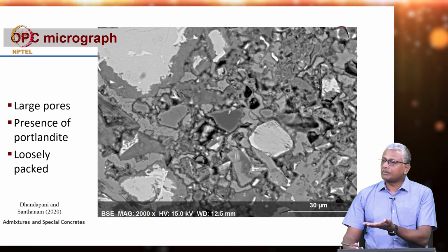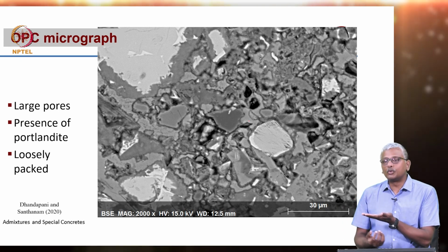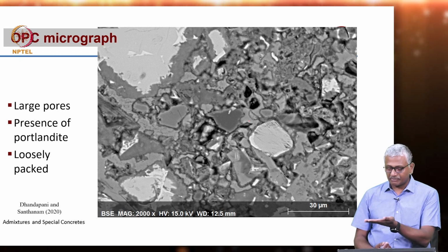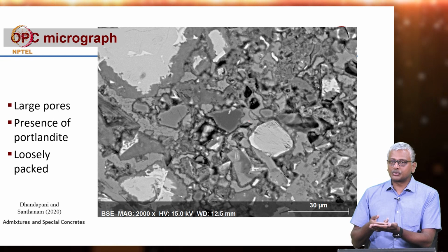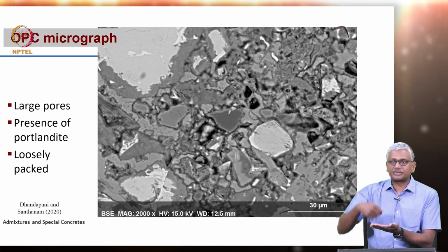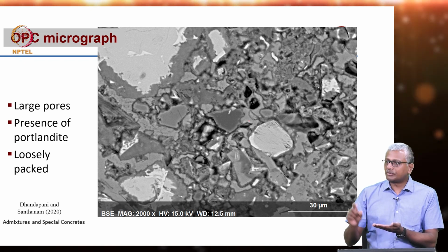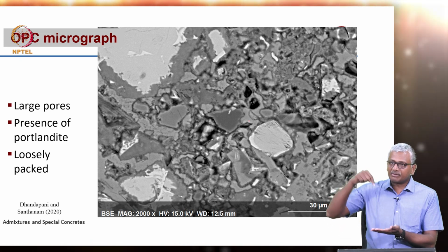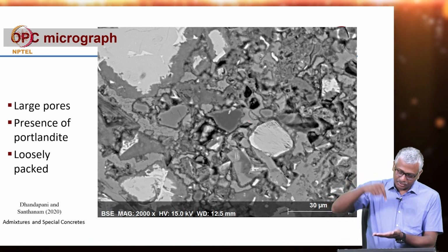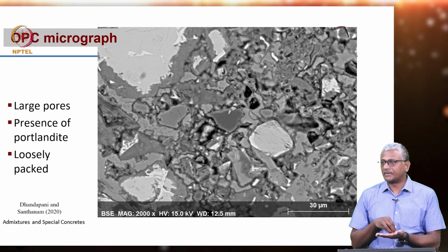So, what happens in light microscopy? We usually, in school you may have done in biology and stuff like that, you have a glass slide and you pass light from underneath and you have a tissue sample that you can then look at from the top. That is called transmitted light microscopy, right. But you can also have, for thicker materials that are opaque, that do not let light pass through, a reflected light microscopy. So, that means the light source and the objective are both on the same side of the specimen, right.